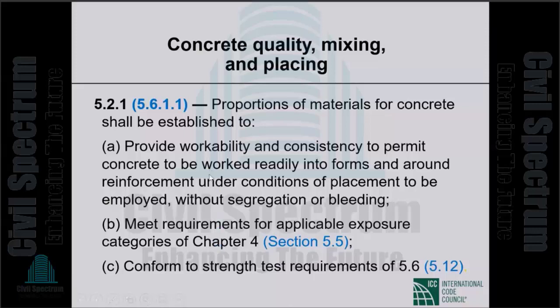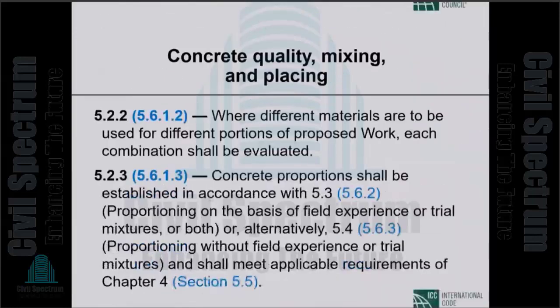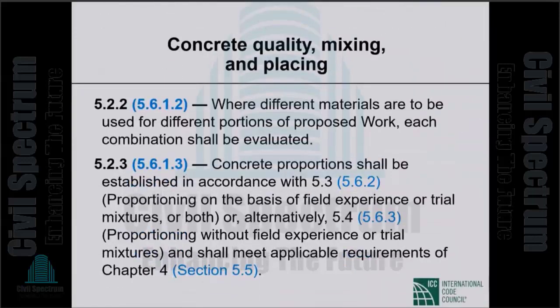The concrete has to be able to go where it needs to go. So that is extremely important. Workability, the durability considerations, and the strength. All three are important in proportioning. Where different materials are to be used for different portions of proposed work, each combination shall be evaluated. Concrete proportions shall be established.